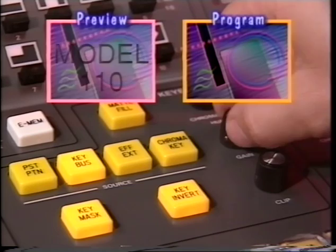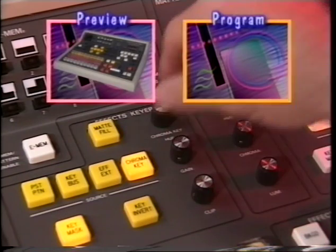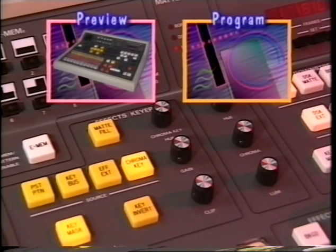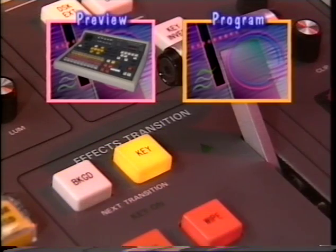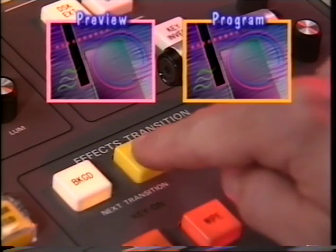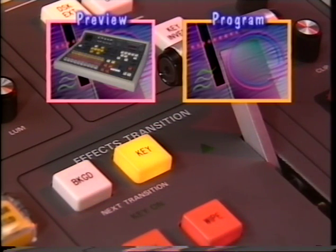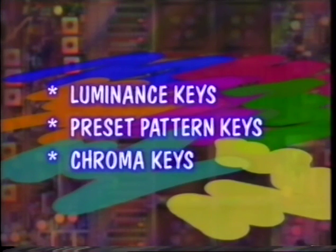Gain adjusts the edge of a key from hard to soft. In the chroma key mode, chroma key hue lets you choose the color from which a chroma key will be produced. A key memory feature is also built into the keyer that recalls the last clip and gain control settings used by each key source. The effects key mode is activated by the key push button in the effects transition control group. 3 types of keys can be performed using the effects keyer: luminance keys, preset pattern keys, and chroma keys.